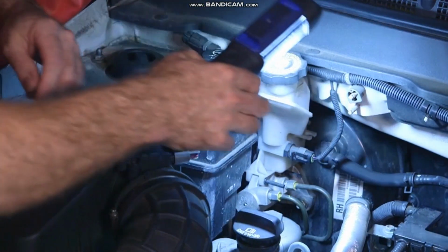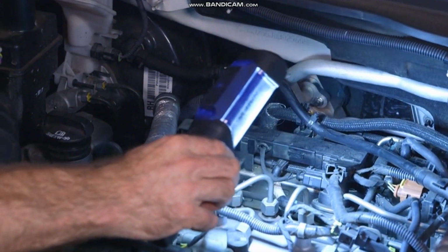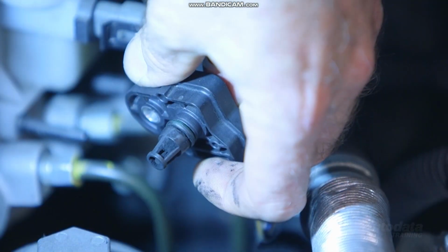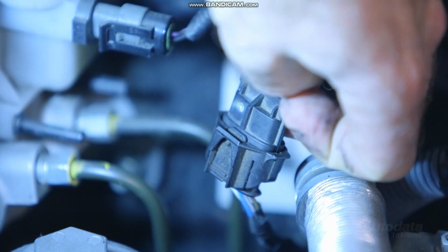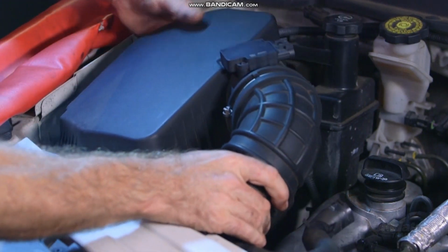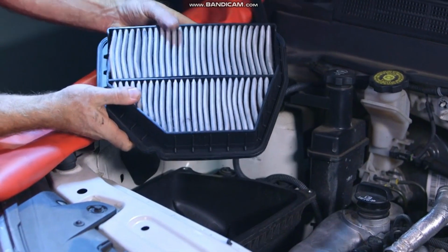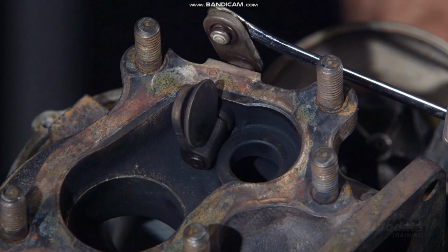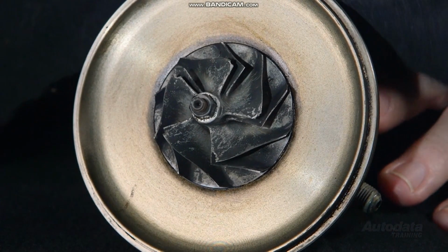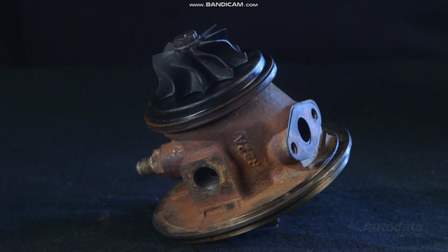If the boost pressure data does not change in relation to scan tool commands, it will be necessary to perform a visual inspection of the system. Inspect the boost pressure sensor for damage, blockages, or a leaking seal. Check the harness connector for security. Inspect the air filter and intake system for damage, modifications, or abnormalities that may allow higher than normal airflow. Check for seized or binding linkages, damaged or leaking vacuum and pressure hoses. Check for sticking, broken or missing components or debris in the turbocharger. Pay close attention to the wastegate.